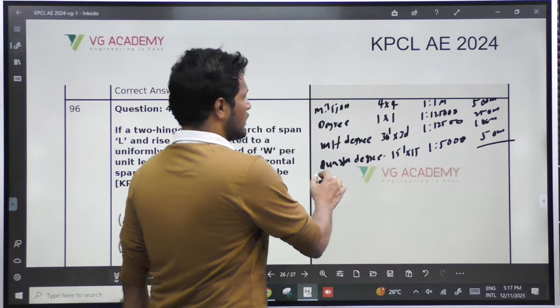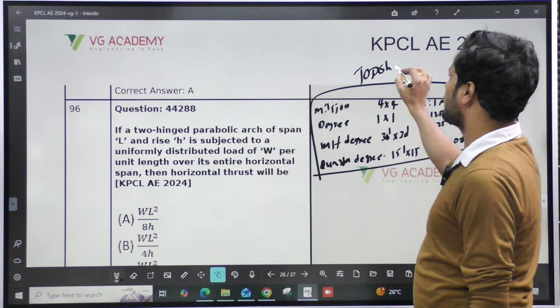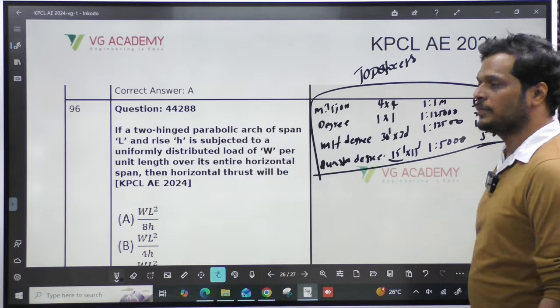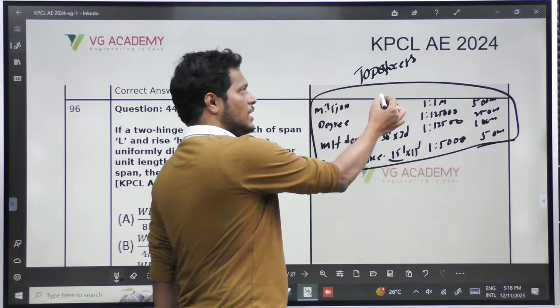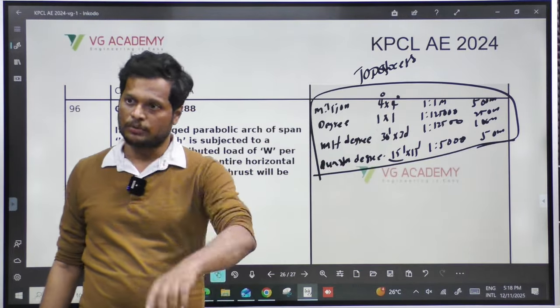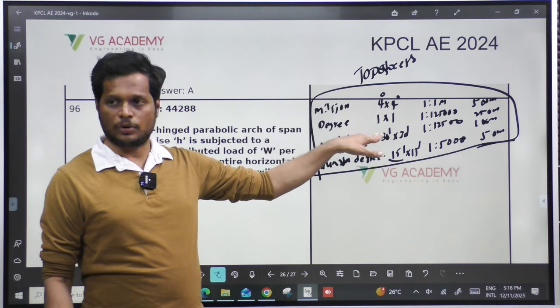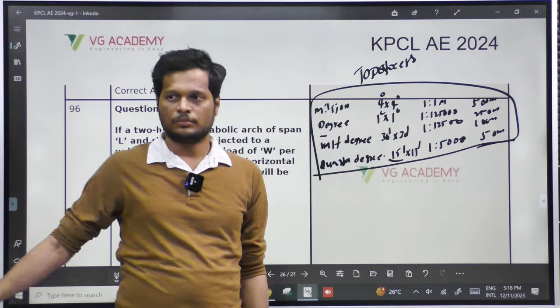Okay, so these are the values. Like this, different topo sheets will be published by the Survey of India. So here they give 15. The first one is the million sheet, where each quadrant is 4 by 4. This is divided by 4, so this is 1 by 1. Each will have only 1 degree now.